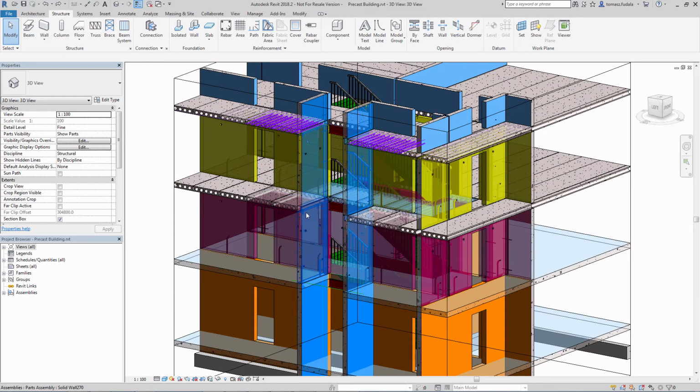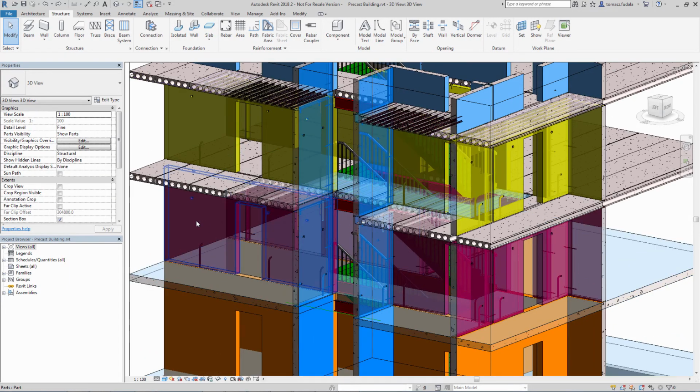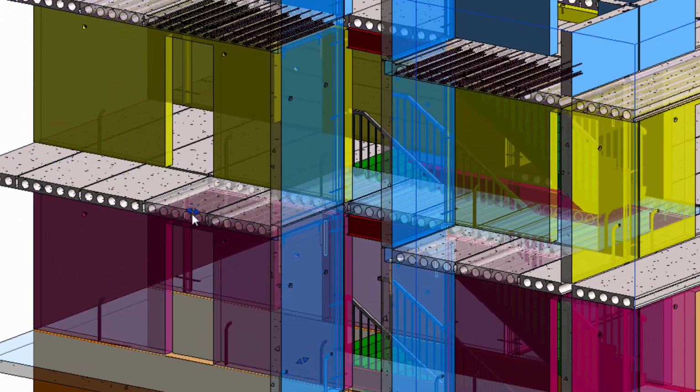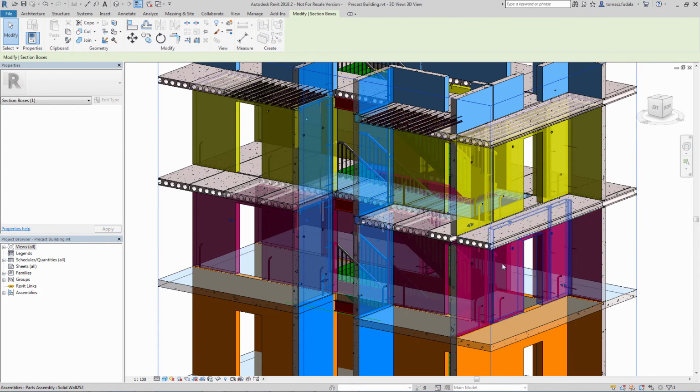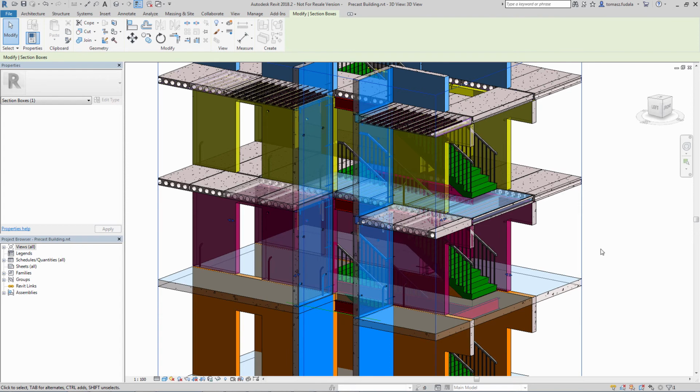Previously in Revit, the blue double triangle controls of a 3D section box needed a very accurate selection to avoid picking up some objects from the model behind them. Now in Revit 2018.2, the section box shape controls have been improved so you can more reliably adjust a section box. All of these user interface enhancements were requested by users like yourself